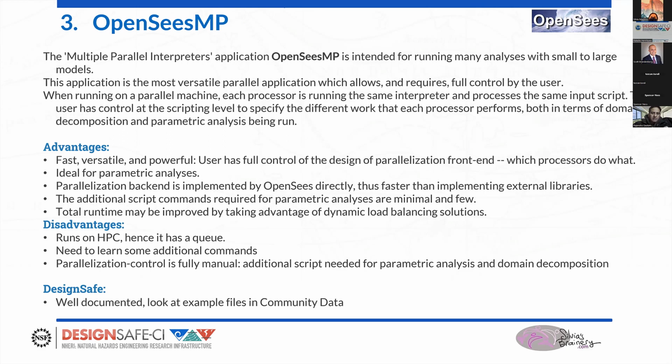You're not really sending different scripts, but within the script, you say, hey, if you're processor 1, do this. If you're processor 2, do this, and so on. So you put into the script which processor does which work, whether it's from assigning which nodes and elements go to that processor, or which analyses are being run by that processor.